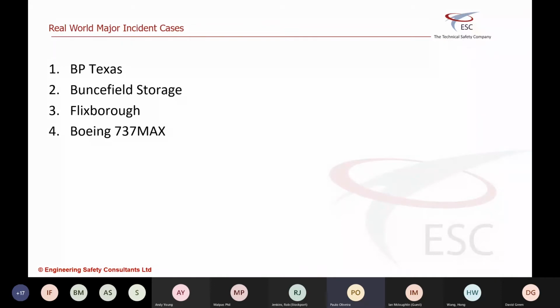The reason why I looked at these is that I wanted to look at risk targets and at demonstration of risk reduction. You know, that warm fuzzy feeling when we say, well, if I have a SIL1 function with a PFD of 2.6 e to the minus 2, and with our relief valve, that gives us 0.01 risk reduction, we go from having an unacceptable level of risk to an acceptable level of risk. Yay, everything's okay. So I wanted to look at that. I wanted to see in these ones, where did the numbers play a part? And I extracted some of the root causes that were identified with these incidents.